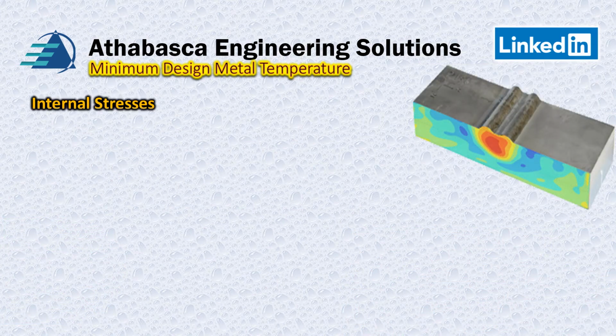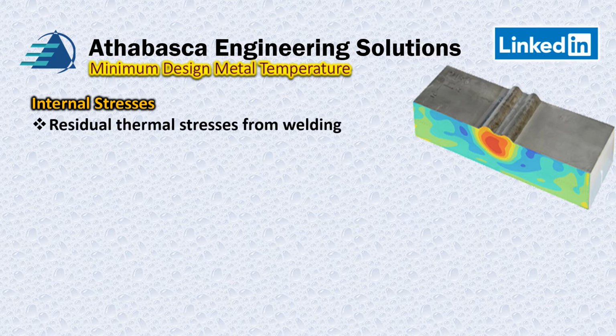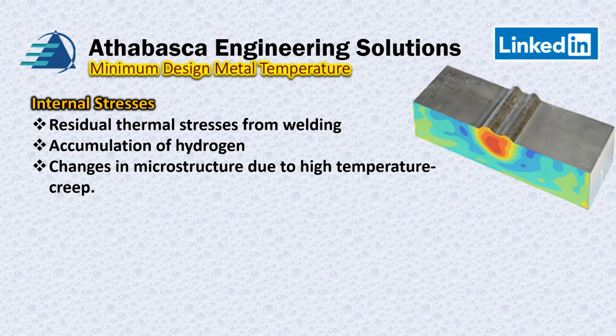Internal stresses can play a big issue on the MDMT as well. One of the most common is residual thermal stresses from welding. ASME can provide a credit for post-weld heat treatment to reduce internal stresses around welds. And accumulation of hydrogen is another one. This can cause embrittlement of the steel and make it more susceptible to brittle fracture when the parts are stressed.